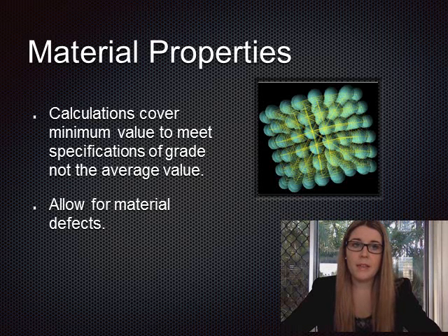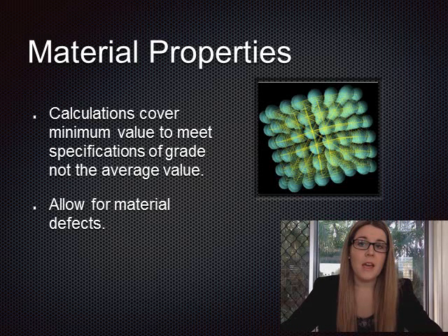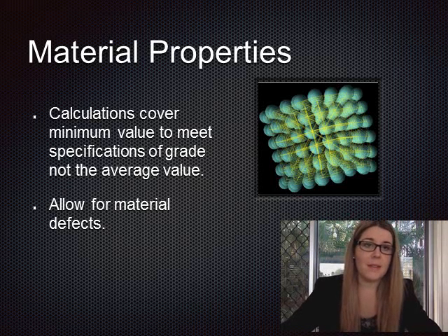So material properties, when determining this factor of safety, calculations must cover the minimum value to meet the grade of safety standards, not the average value. You should also allow for material defects that may occur.